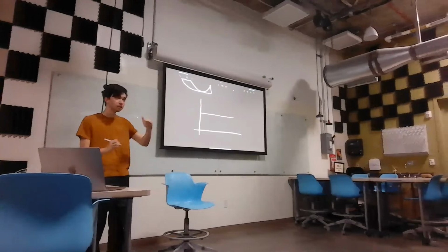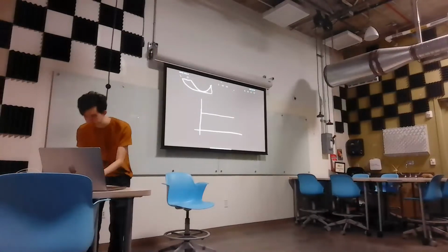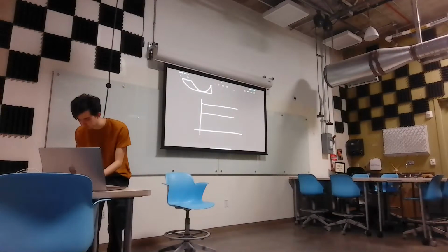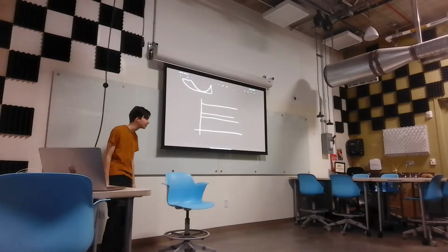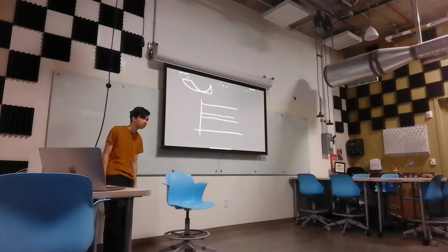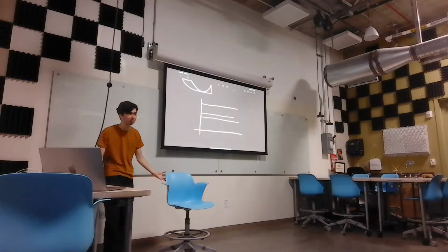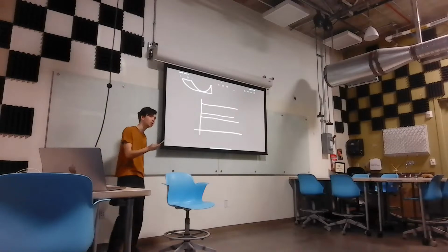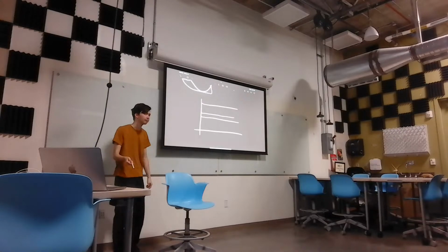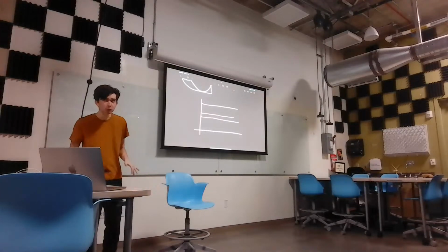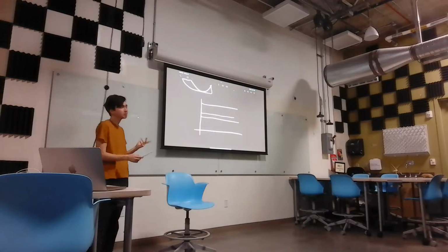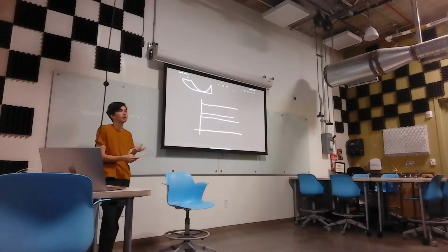But the only two closest duty cycles will give us this voltage or this voltage. Which one do you pick? That's a trick question. You pick both, for certain amounts of time. Since this one's a lot closer to the bottom one, we should probably be at the bottom one more of the time.